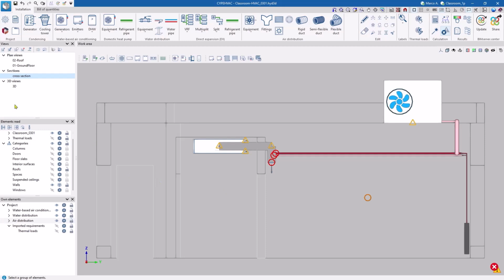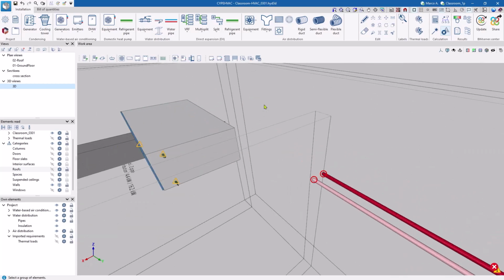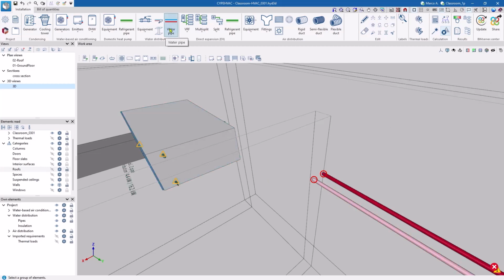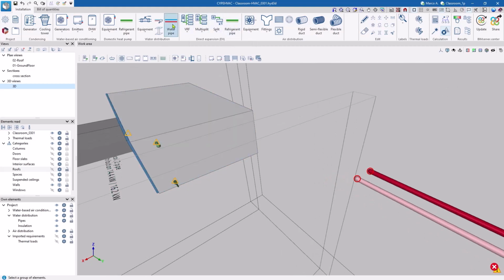We have defined the duct layout, but we have not yet connected the fan coil to the roof generator. We simply connect the corresponding inlets and outlets with pipes. Considering that we have the supply and return connections that supplied the radiators, we can use them to connect our fan coil, while always respecting the directions.